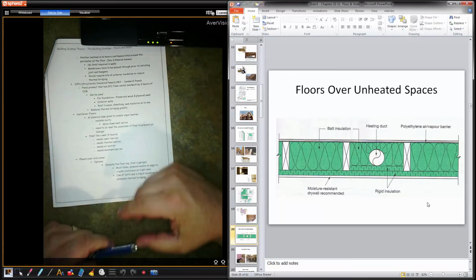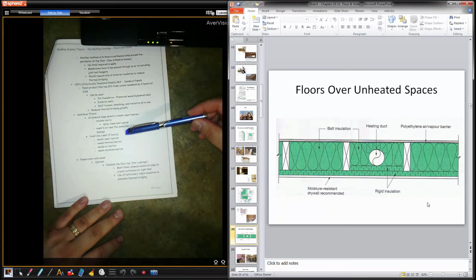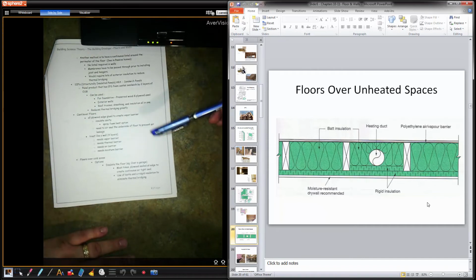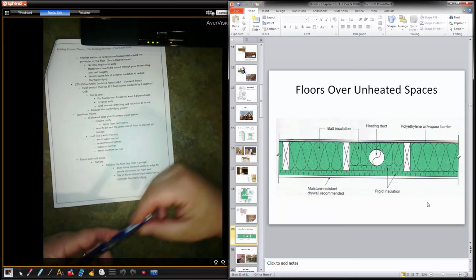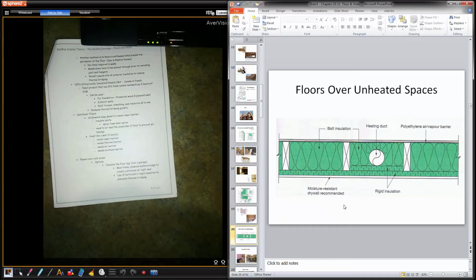So the best thing is floors need to be treated like a wall. Vapor, thermal, air, moisture. Right? Just because it's a floor doesn't mean there's no air going to reach the underside of it, especially if it's a cantilever floor. A cantilever floor could be from the second floor walls. Right? It could be coming out over top of the first floor walls, and the second floor walls are sitting on top of it. So lots of wind pressure coming in, hitting the wall and bouncing up.